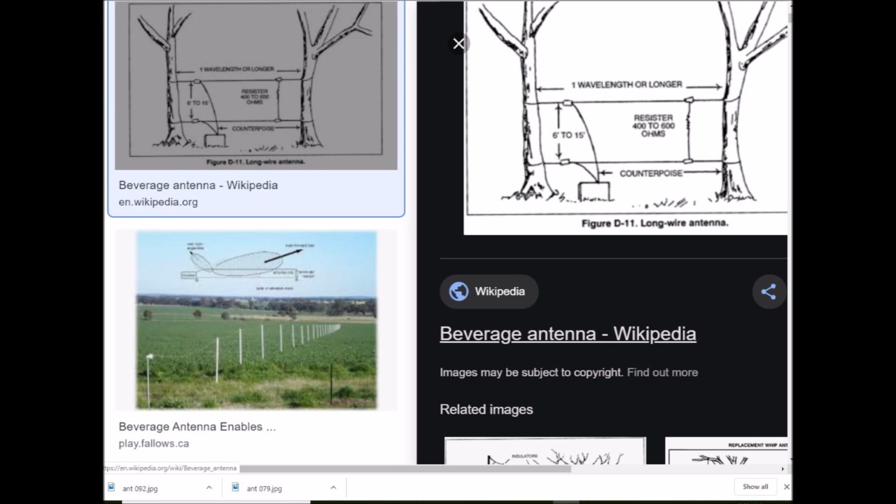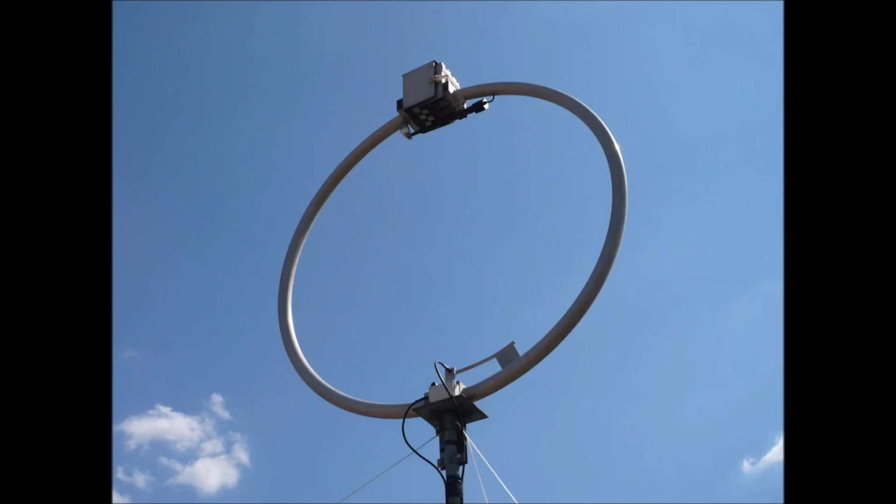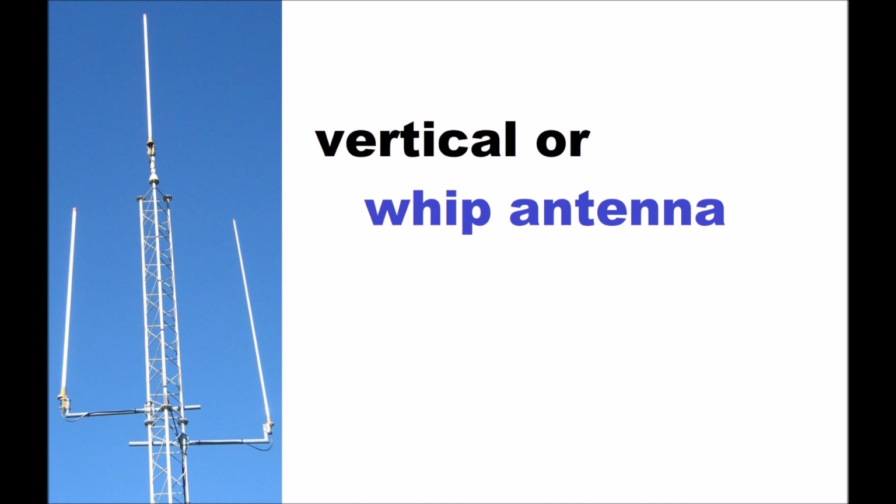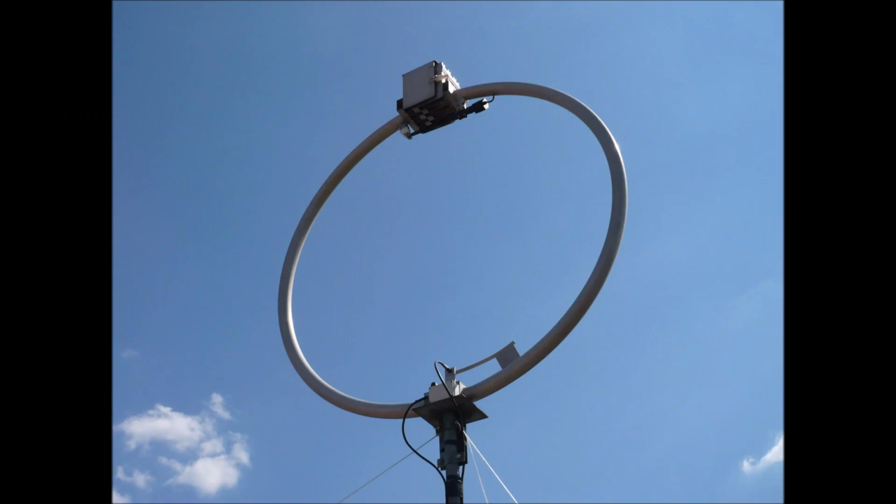can have significant directivity. For non-directional portable use, a short vertical antenna or small loop antenna works well, with the main design challenge being that of impedance matching. With a vertical antenna, a loading coil at the base of the antenna may be employed to cancel the reactive component of impedance. Small loop antennas are tuned with parallel capacitors for this purpose.